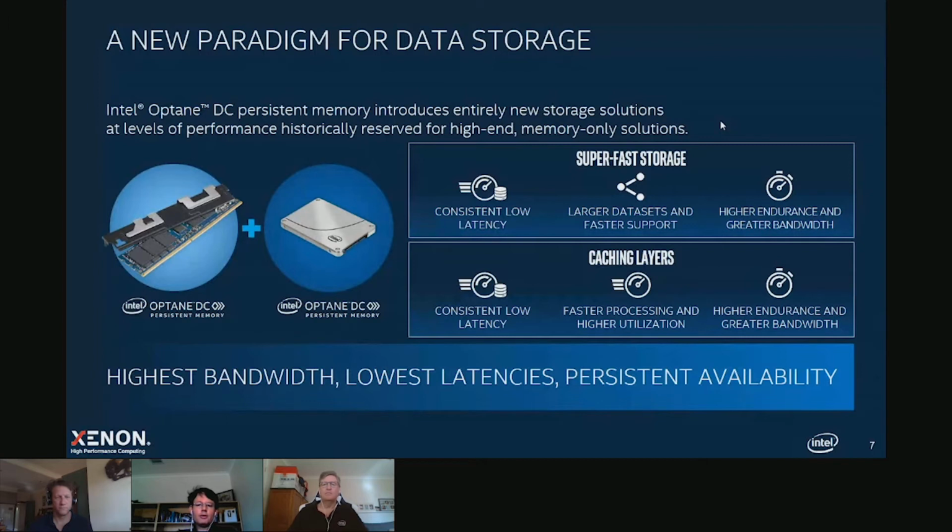And Optane also has the advantage that it has much higher endurance than conventional flash SSDs, which suffer from wear out problems, especially in the triple level cells and in the new quad level cell designs. That's really where Optane shines, that it does not have the endurance problems. And on top of that, it has much greater bandwidth, which overall leads to much better storage performance.